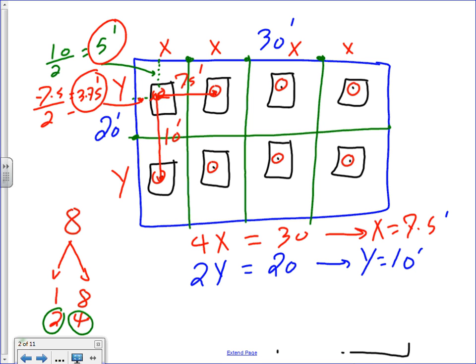I need to identify the X and the Y so the electricians can go there and place them. Here's how you identify the X and the Y. The rule, guys, is the distance from the wall to the center of the fixture is X. The distance between the 2 fixtures is 2X. When you put a fixture, you go from the wall 2 feet, and between the 2 fixtures, 4. The distance from the fixture to the wall is half the distance between the two fixtures. That rule can give you the best distribution. Can I have a thumbs up, Chad?